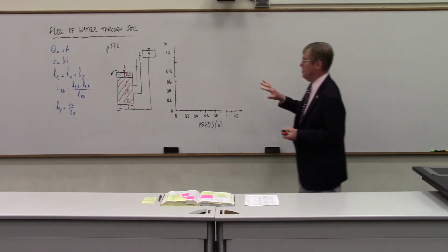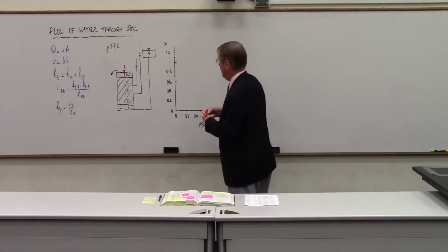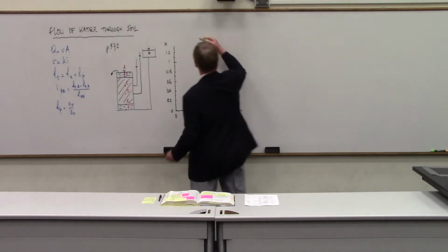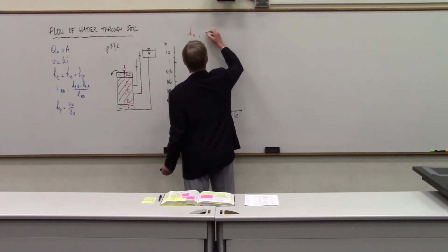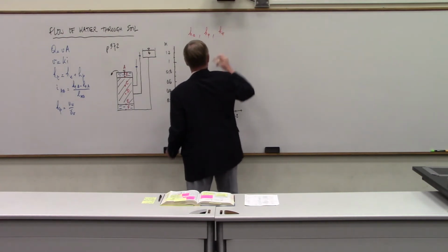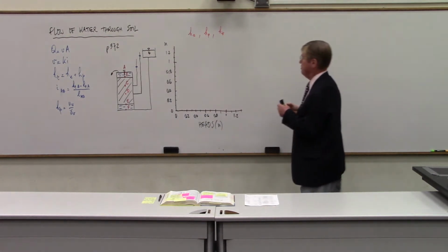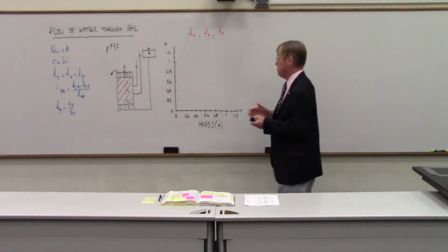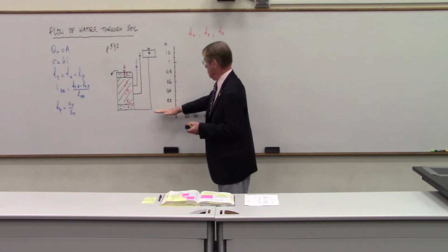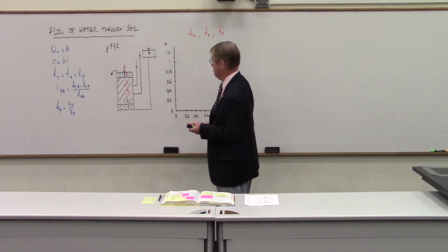Okay, the question is, draw the diagrams for elevation head, for pressure head, and for total head. We're going to do that. The easiest is elevation head, because it's simply the height above the datum, above zero.